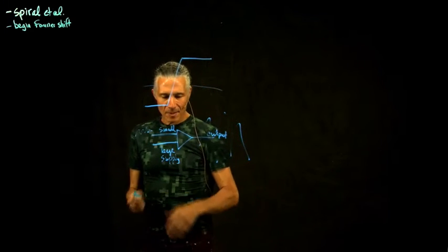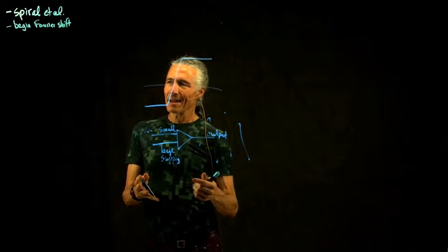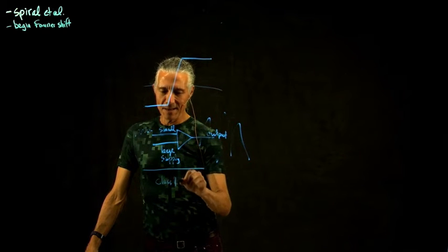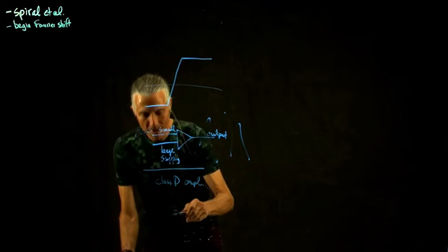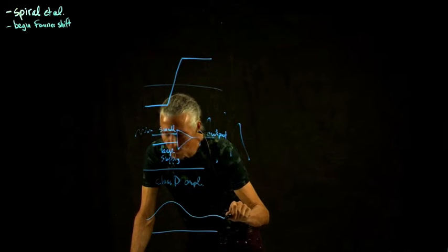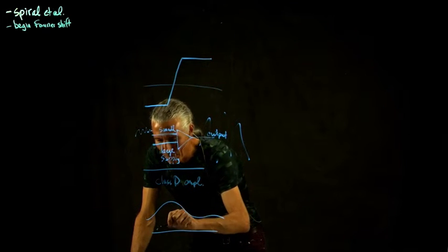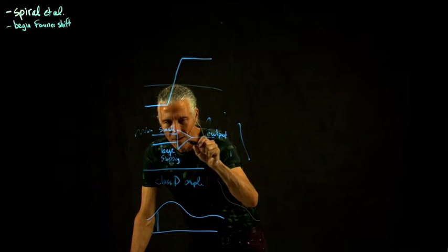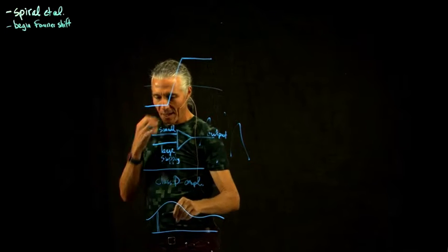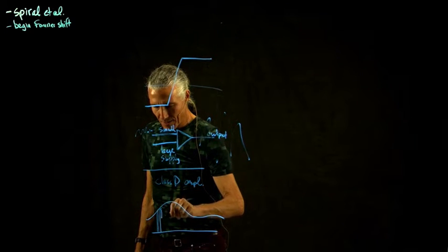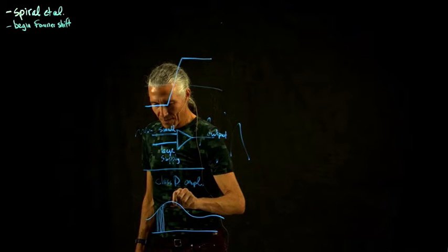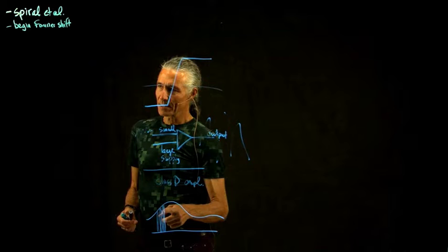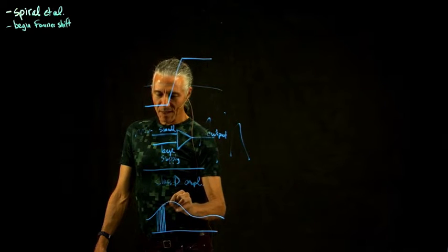I mentioned last time that that's actually not the way. That would be like a class A or a class AB amplifier. But we mentioned that the gradients have class D amplifiers. What those do is they essentially approximate some smooth curve by just turning on and off, using a transistor just like a switch, switching it on and off very rapidly, like at 100 kilohertz, 100,000 switches per second, and you approximate the waveform by these little pulses. Now, how do the pulses get smooth? That's a little complicated part.